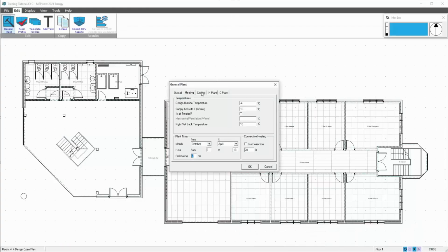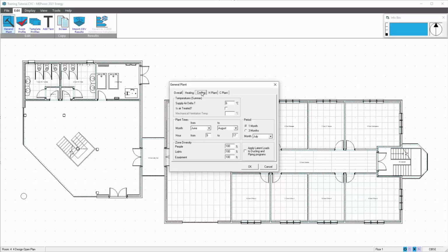The same principles and parameters are applied to cooling. So in this case again we'll look at the results with direct ventilated fresh air from outside using the temperatures from the weather database. So in this case the cooling is driven by the weather database for the peak months of the year, which is usually June, July, August, or July, August and September. So you may well be ventilating air into the space at 28-30 degrees, which will obviously have a bearing on the gains to the spaces, and then you decide whether you're going to pre-cool the fresh air as explained previously.